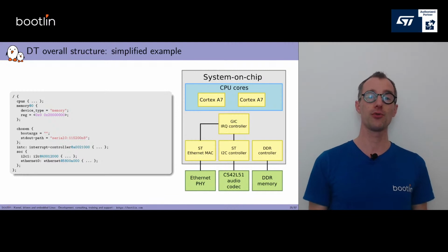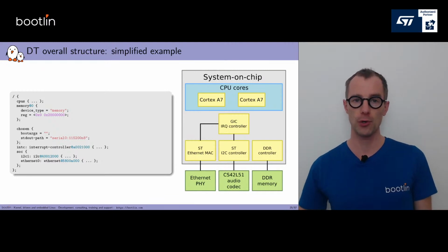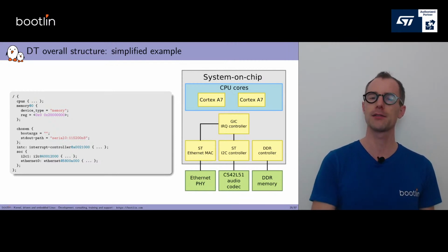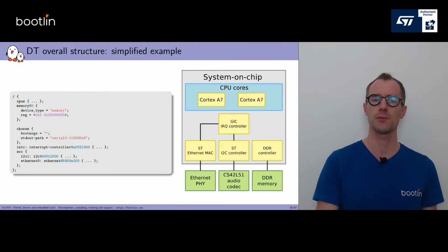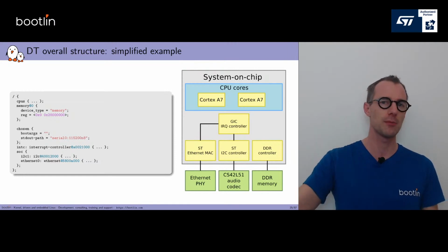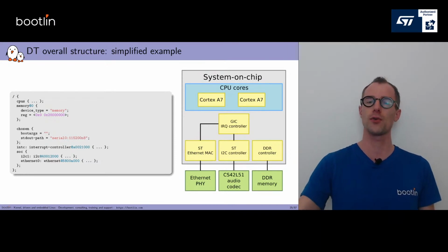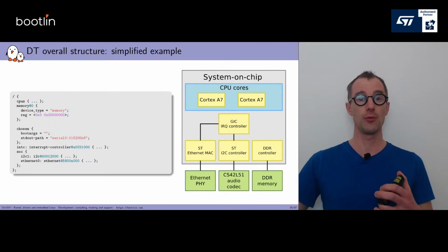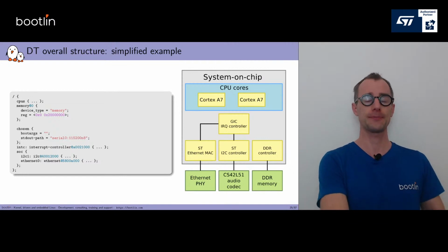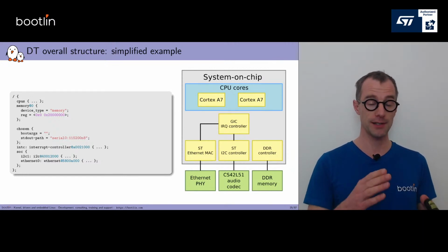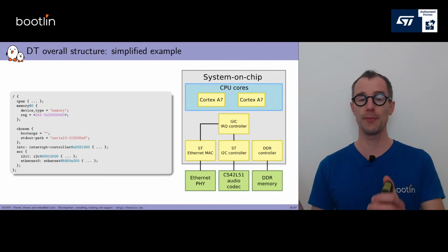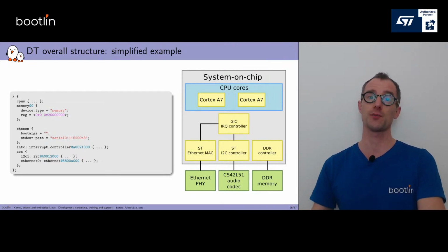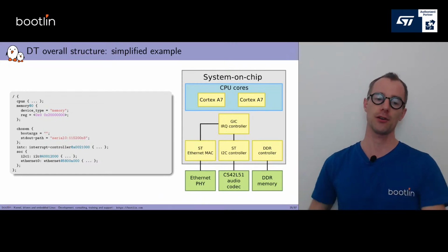The other property, bootargs, is used by the bootloader to pass to the kernel the Linux kernel command line. The kernel command line is this line of instructions where you specify root=/dev/mmcblk0p3 to indicate the location of your root file system, or many other kernel arguments. And so the way the bootloader passes that information all the way down to the kernel is using this property. Your bootloader updates the DTB, and specifically this /chosen/bootargs property, so that it passes that kernel command line to Linux.